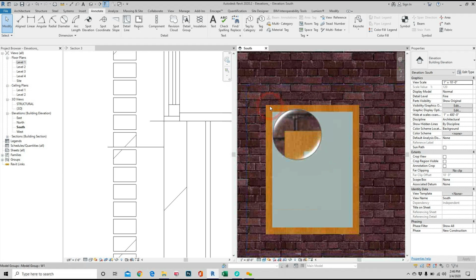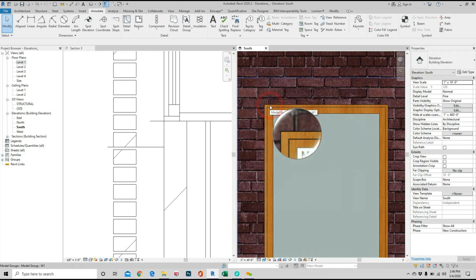So once I do that, if I had a stone lintel or something, we would go, like Professor Ackerman said, 8 inches. I know it will use 3 bricks above that. So when I'm designing the lintel, I make it 8 inches high on purpose. Now, if I did a soldier course, how tall is that? 8 inches, because it's the brick. So you see how these modular dimensions start coming up.